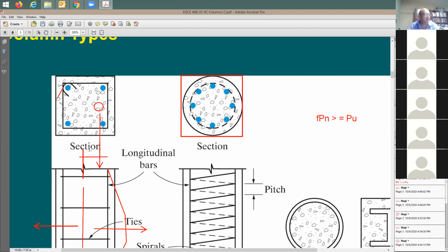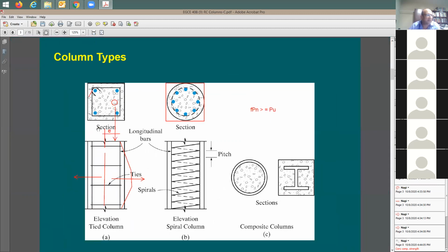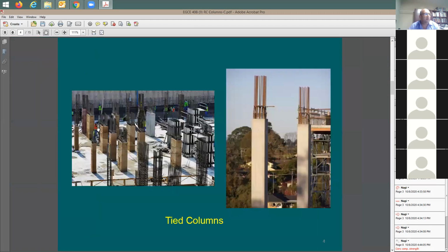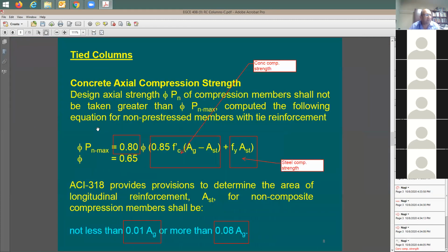And this E is causing moment on the column. So this axial load multiplied by this E is giving you some additional moment. And as long as you have a very small amount of moment, you call it small eccentricity. So as long as you have this within this small eccentricity, your equation is still valid, and you don't really need to check the moment demand on the column. Instead, you just provide here 80%, which is reduction of the concrete column strength. So what is this 0.8? I'm going to say this gave you for a small eccentricity effect.